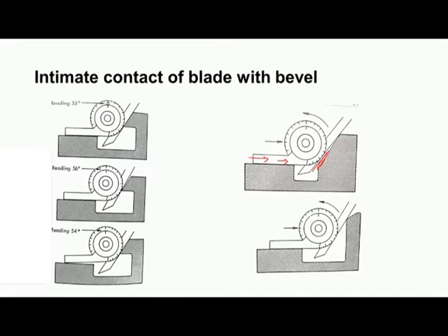If we further push the instrument, you can see here when we push, there will be a proper contact like this, and if we try to push further, again the sliding blade further rotates, and then there will be error in the reading. Such things should not be there. So, while using this bevel protractor, the surfaces of the workpiece should be properly cleaned, and the surfaces of the blades of the bevel protractor should be properly cleaned, and then we should carefully use the instrument.